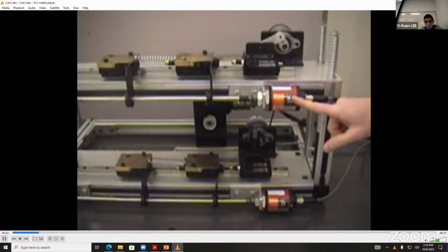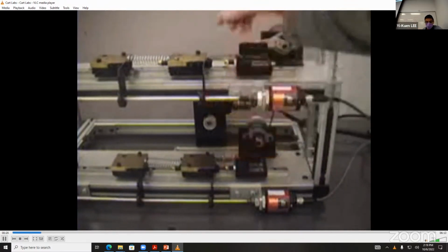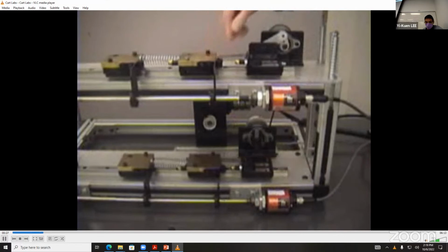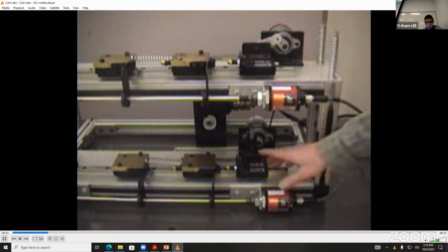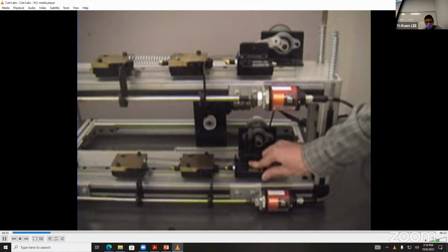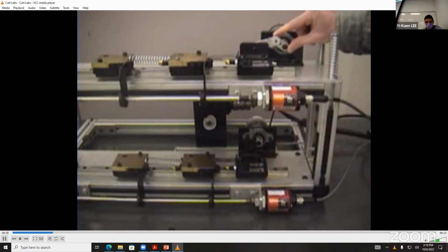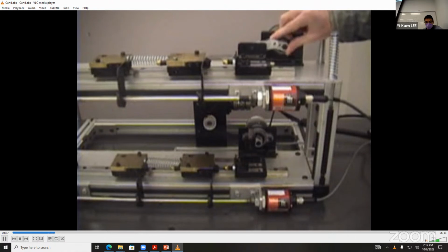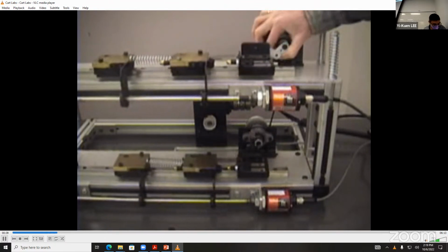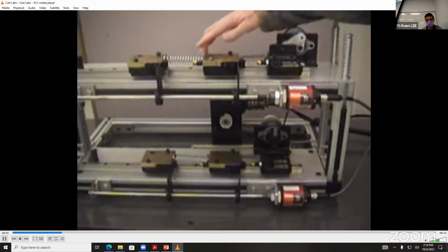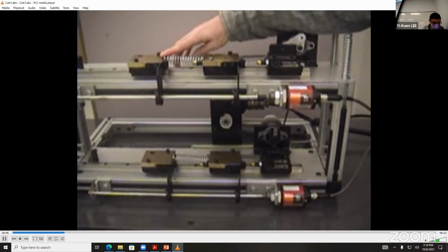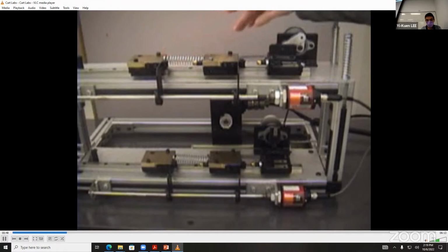We have a magnetostrictive sensor that records the position of this input cart as the slider crank moves. One difference between these two linkages is that the Scotch yoke provides pure sinusoidal motion, whereas the slider crank has two frequency components: the main frequency that it's being driven at, plus twice that frequency, a higher harmonic. We'll see that effect when we drive the spring mass damper. We'll notice resonance at two different frequencies.